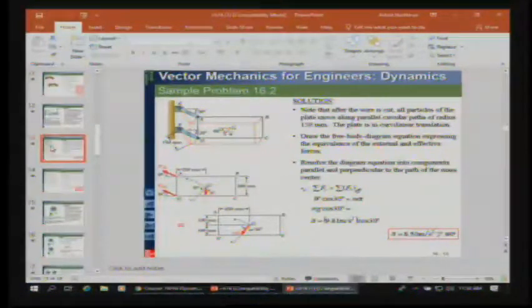They're parallel circular paths. So point G is moving along the same sort of path, a curvilinear translation, and it's going to be parallel to a circular path described by any other point on the plate, including points A and D. It's not true for the links in general. It's just true for the points A and D because they're also on the plate.